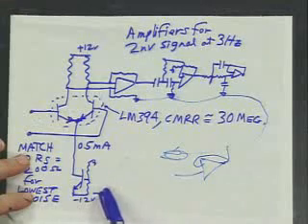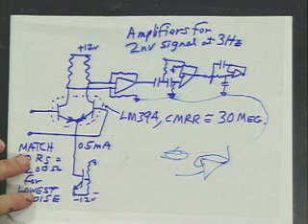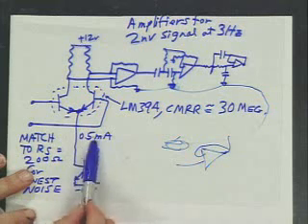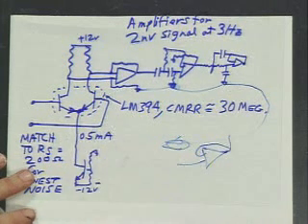So you're running enough current through here to get the voltage noise down, but not too much current, because then your current noise goes up. If we ran too much current, that would be excessive, it would be a disaster. Isn't analog beautiful? Analog is very hard to get exactly right. Picking half a milliamp wasn't arbitrary, folks. It could be 0.6, could be 0.7, could be 0.4, but we're in the right ballpark to have low noise.